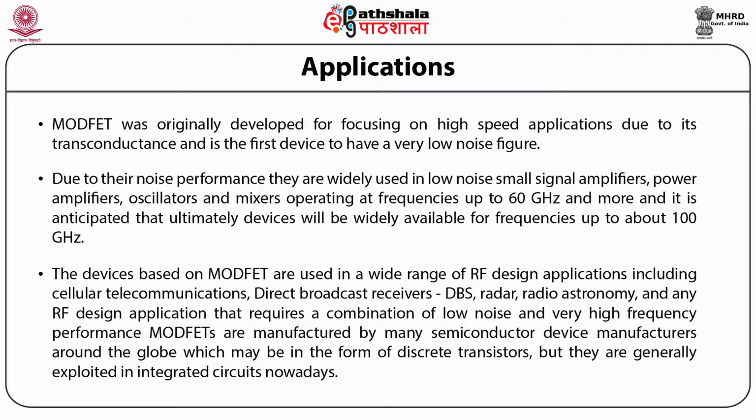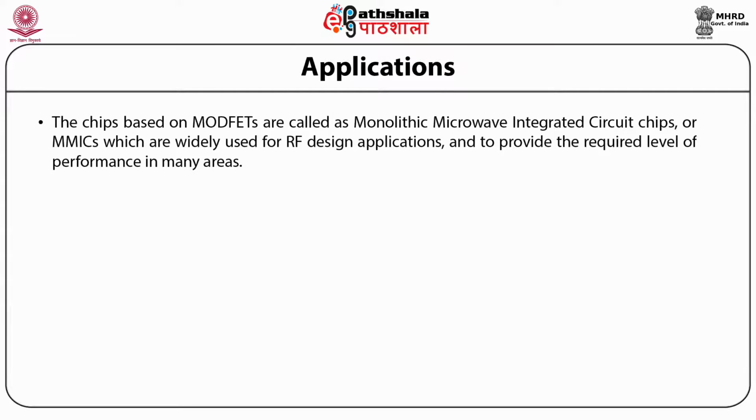MODFETs are also manufactured by many semiconductor device manufacturers around the globe, which may be in the form of discrete transistors, but they are generally exploited in integrated circuits nowadays. The chips based on MODFETs are called monolithic microwave integrated circuit chips, MMICs, which are widely used for RF design applications.